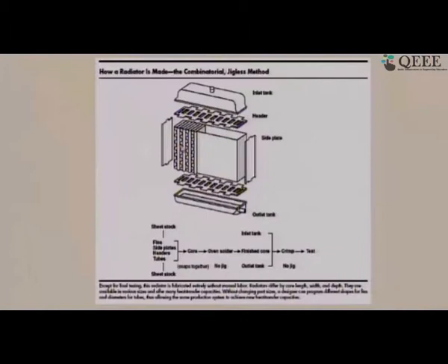And to keep it cool, between these plates we have put a lot of thin aluminium sheets of this shape, which are called fins. So we have hot fluid going inside the tubes and giving energy to the tube material. From there it is conducted into the fins and also given to the air, and air is being sucked or blown through these passages on the outside, which causes convection heat transfer on the fins and the outside surfaces of the tube.